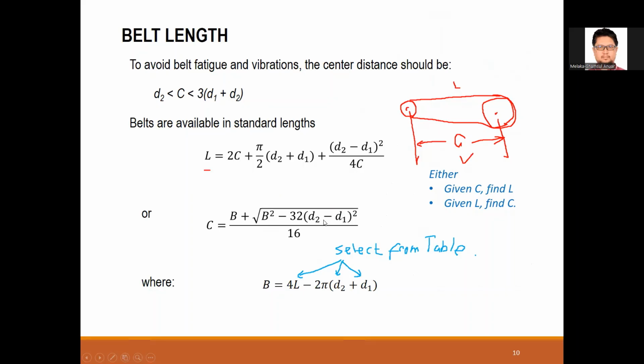What you want to also look at is the belt length. You can calculate it if you have decided what your center distance between the two pulleys or shafts. If this information is not given, you can try to get somewhere in between.